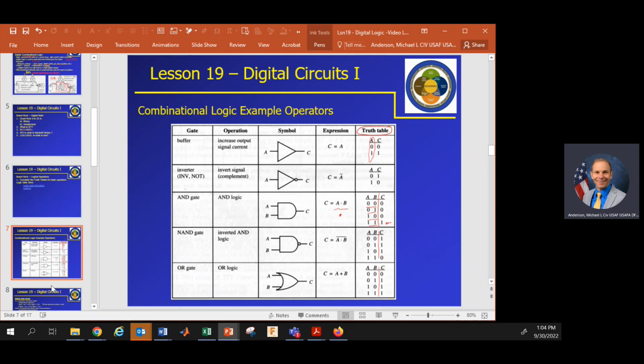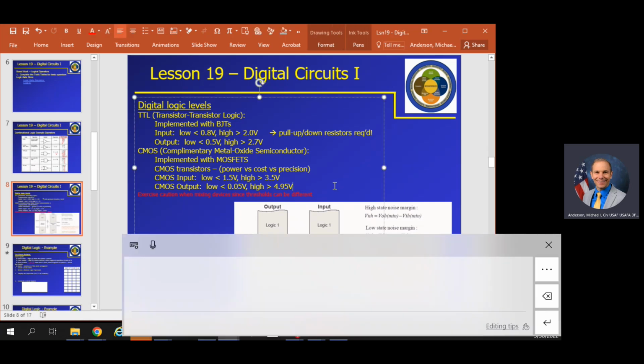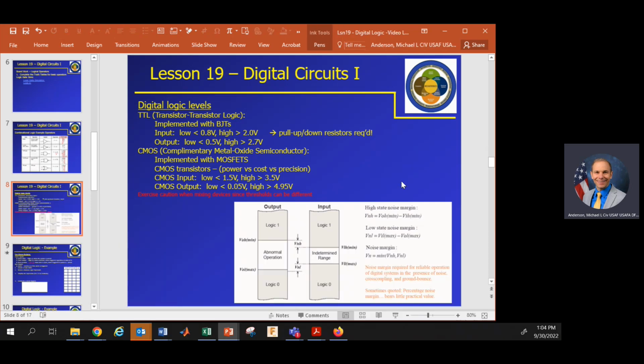You should study those and know how they work. One important point here is we're going to actually implement these in digital devices. And one of the first things you'll do in the next lab is test when your Mega thinks an input is high or low, and it actually changes depending on if you're switching from high to low or low to high. So that's a really important thing to understand.